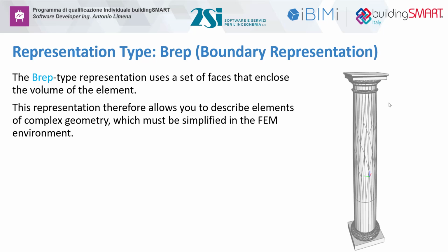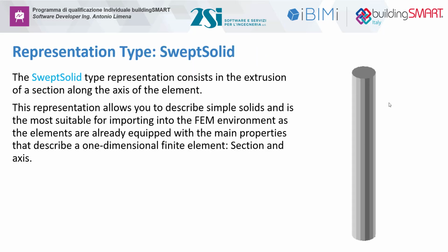If I would model this in a FEM model, I will just represent it as a cylinder, so as a circular section extruded along the axis. And that is exactly what the swept solid representation type does. So this representation allows you to describe simple solids and is the most suitable for importing into the FEM environment, as the elements are already equipped with the main properties that describe a one-dimensional finite element, so a section and an axis.